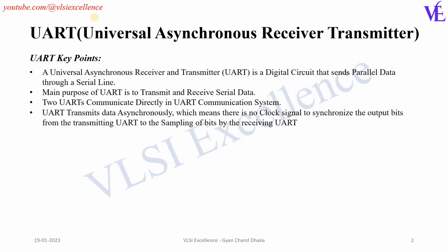So let's understand a few important key points related to UART. A UART is a digital circuit that sends parallel data through a serial line. The meaning of this statement is, suppose we have a UART controller, let's assume it is a UART TX controller. This TX controller will receive some data in parallel form, and that data might come either from some memory or the CPU can write the data in parallel into some register of this TX controller, and then this TX controller will send that data serially through its TX line.